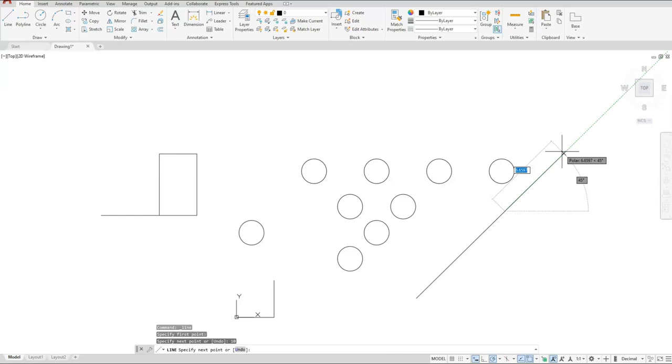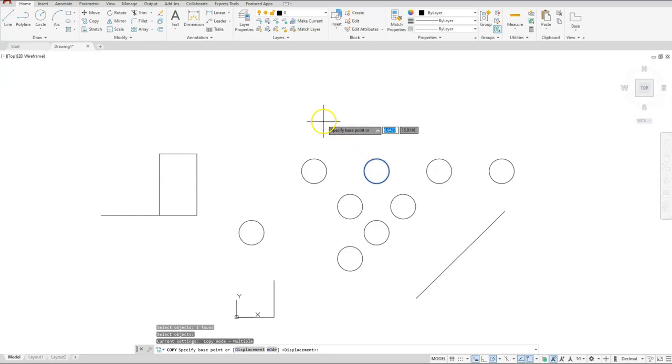So you can remember earlier when I was creating the circles or copying these circles, which is what I'll do now, I had to remember what angle they wanted. Well, with this, I can use a copy, select the circle, pick any base point I want. Once again, I'm moving at a distance. But if I wanted to go 3 units going this way at 45 degrees, I can just simply type in 3.